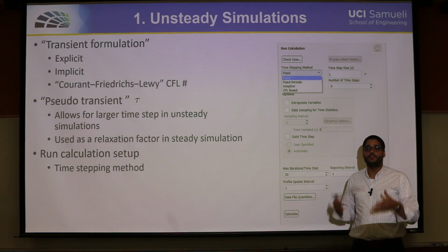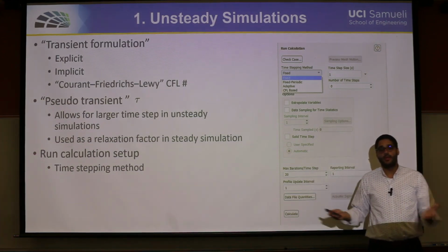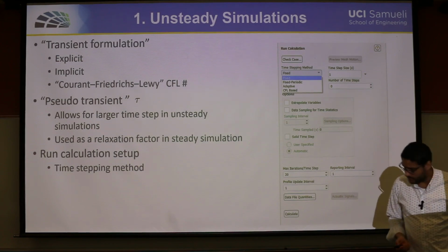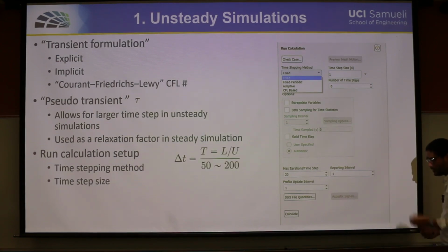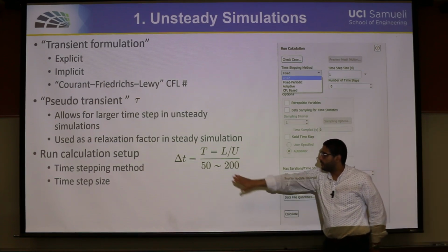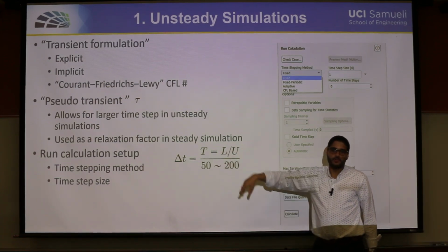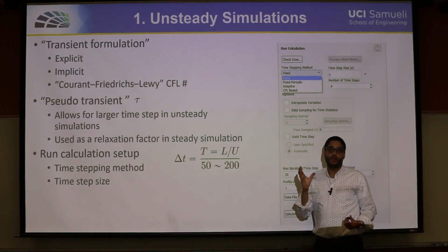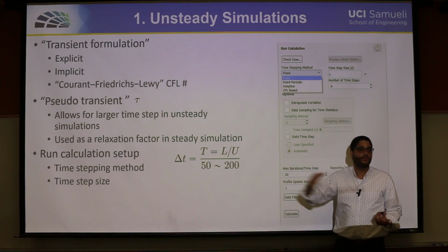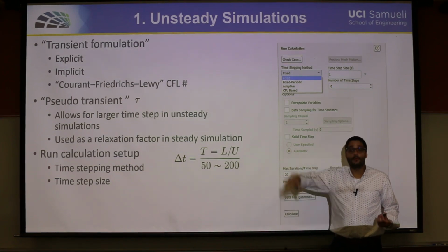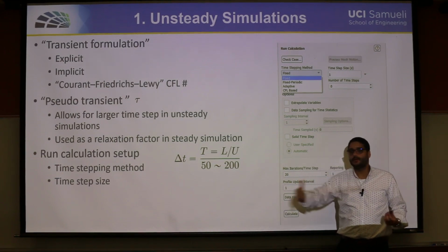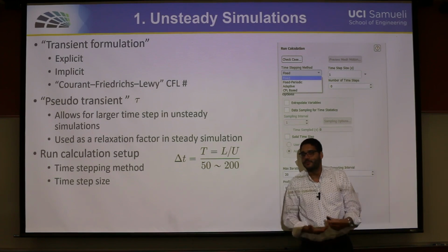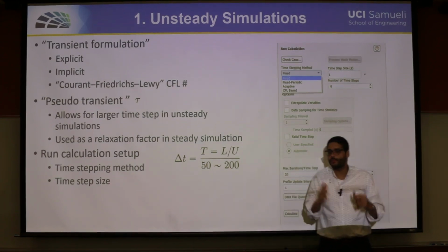So we have a way of defining the grid elements over any mesh or over any fluid domain. But what about the time step? This is a very important discussion. For the time step, what I do on a personal basis, based on my experience, is this: if your body is not in motion, you are not solving a dynamic problem, a moving airfoil or a rotating body or anything, it's just a fixed body in the Eulerian frame of reference, and the wind is blowing over that body.